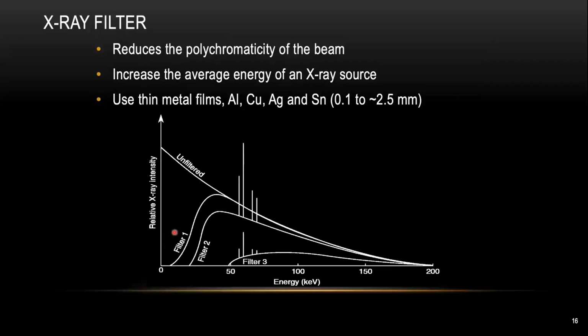Earlier I mentioned the filter. The X-ray source we use for micro-CT imaging is not monochromatic X-ray, like what is used for the synchrotron. It's a polychromatic X-ray source, which means it gives you a spectrum of energy from low to high. But if you're working on a piece of very dense metal, you only require high-energy X-rays to get signal to penetrate through the sample.